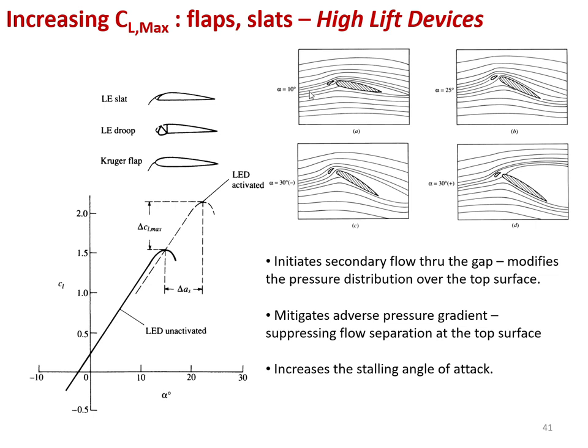As you can see, there is a streamline passing through that gap between the airfoil and the flap, and then reintroduced to the top of the airfoil. This is going to increase the flow attachment to the system, which means that it will definitely delay the stall.